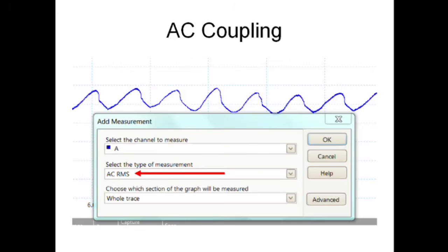Now, I have one more diagnostic tip that I want to share with you regarding fuel pump testing. When you are doing pattern observation or trying to figure fuel pump speed, because you're closely looking at the shape of the different contact points between the armature and the brush, I want you to utilize a feature in your lab scope.